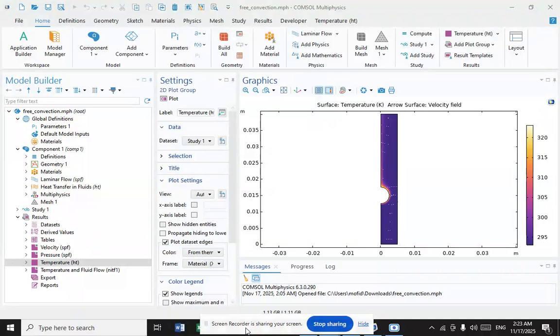For small temperature drops in a flow, the relation ρ(T) may be considered linear, where ρ0 is the fluid density at temperature T0, and β is equal to minus the derivative of ρ with respect to T divided by ρ, the volumetric coefficient of thermal expansion. Numerical values of β are usually small, and therefore the density variation is taken into account only in those cases where it affects the gravitational forces.